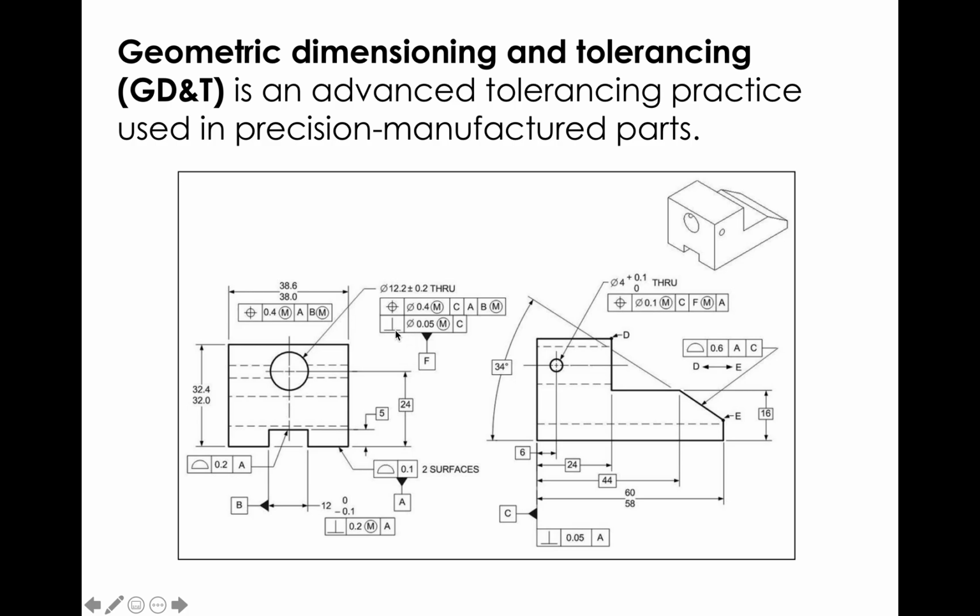So this perpendicular here is calling out basically that the long axis of this cylindrical hole is going to be perpendicular to the rest of the part within a certain dimension. You also have dimensions for flatness, perpendicularity, circularity, all of that.